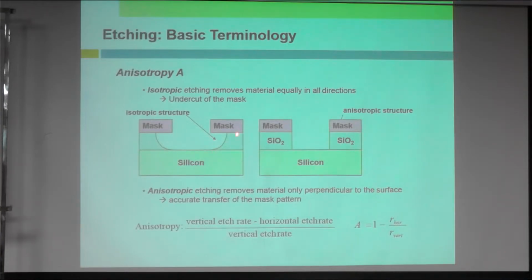So that's why undercut happens. So meaning to say, if you have this size of distance of, for example, 50 micrometer or 10 micrometer, here it might go undercut of a few micrometer to the side.